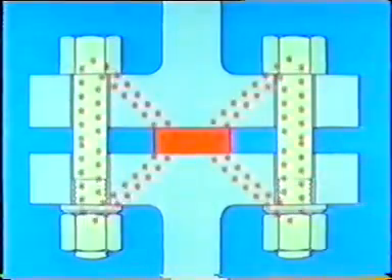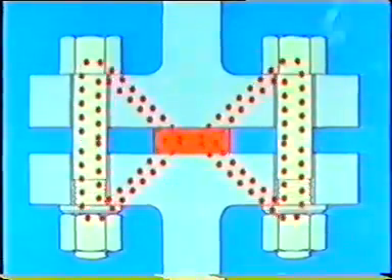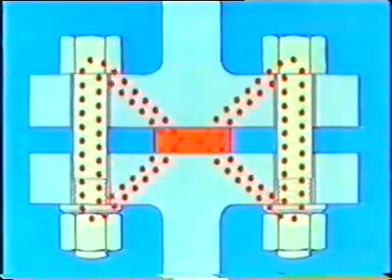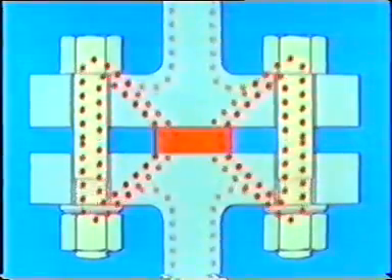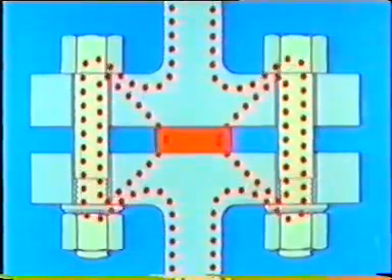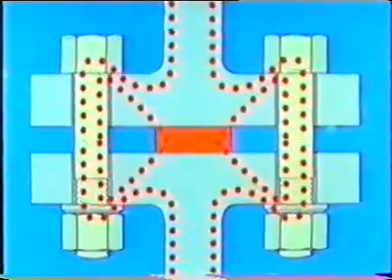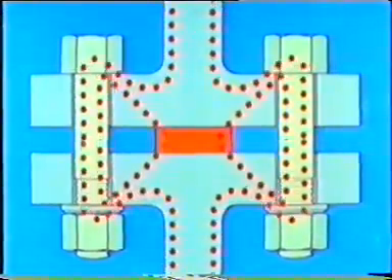Now, a steel strip is placed between the structural components. The contact pressure between the flanges, produced by tightening of the bolts, is concentrated in the strip. The axial force is now transmitted through this connection by reducing the strip contact pressure. The bolts remain statically stressed and fatigue is avoided.